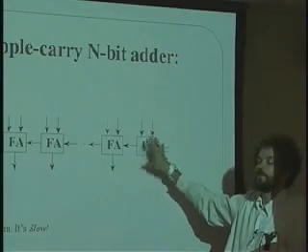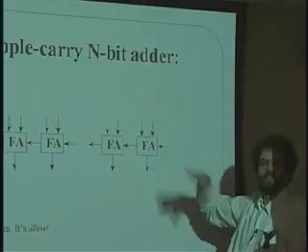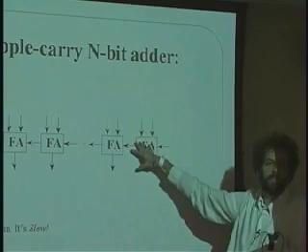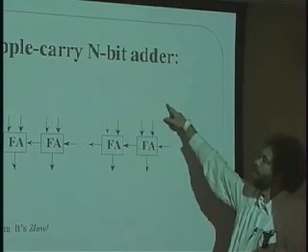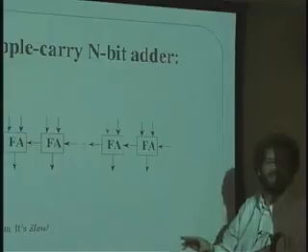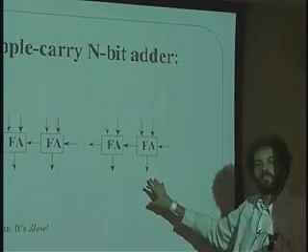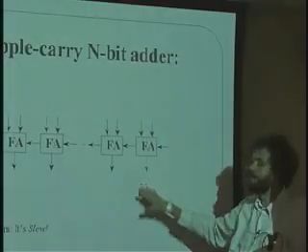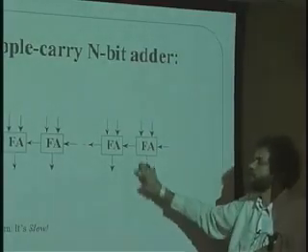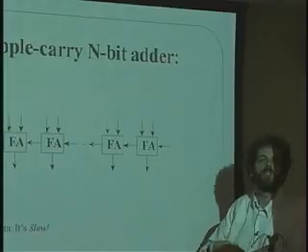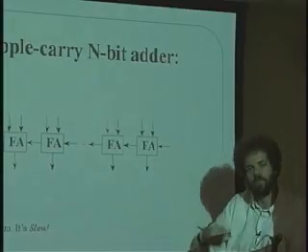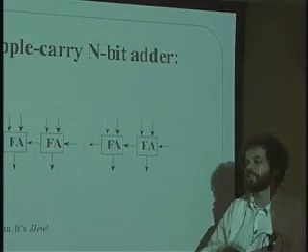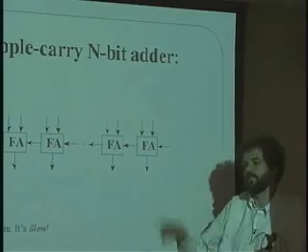You can actually build a system with no clock at all. They're called self-timed systems, where in addition to the data that goes into an ALU like this, you have a start pulse that says, okay, go. What comes out of the ALU is not only the answer, but a finish pulse saying, I'm done. As soon as that's done, the next piece of circuitry that depends on the data is triggered, saying, okay, you start. These little start pulses chase each other through the circuit and loop back and start all over. The system has no clock other than these start pulses going around and around.